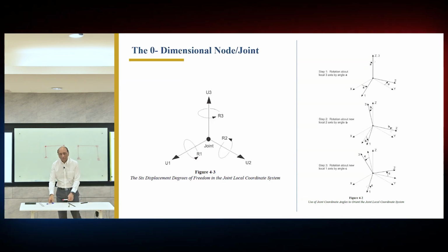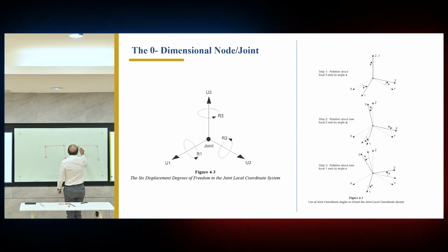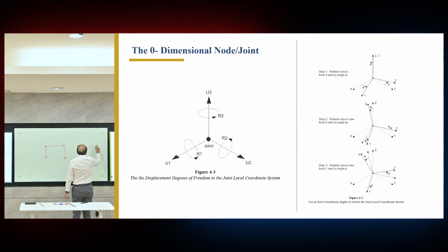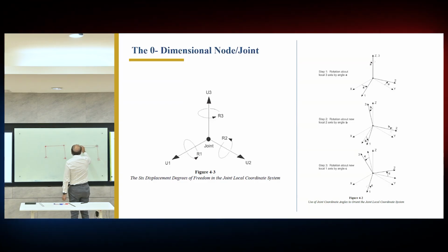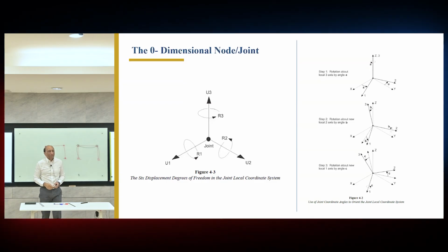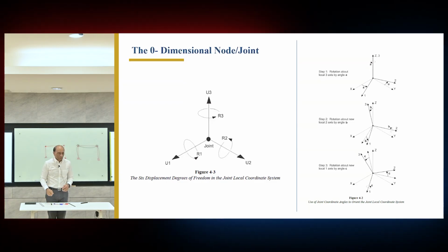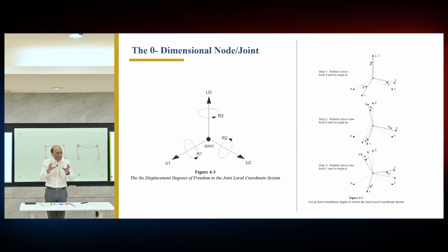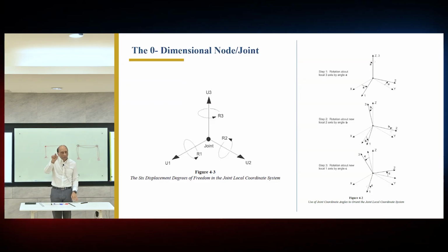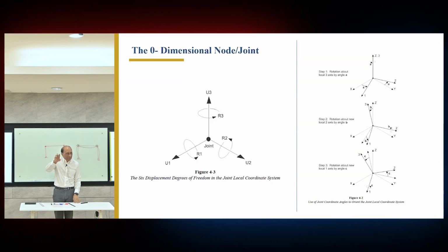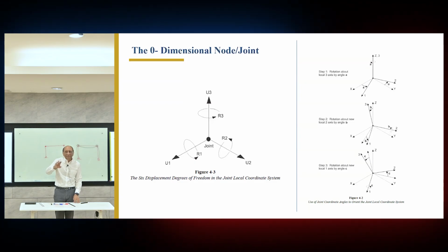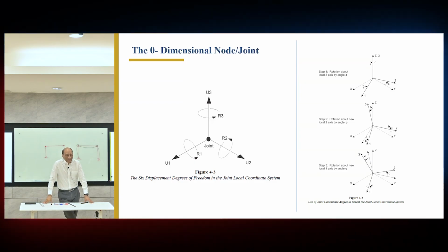And later we realized why he was doing that, because when you deflect this one like this, this will rotate. The node will rotate, and then it will tell you how this will reflect. Because at the joint, members have to remain perpendicular, 90 degrees. So it was a very good way to quickly visualize the deformation of a structure, because if you start with square node, the node should remain square after deformation, and all members entering the node must remain at 90 degrees. So that can automatically give you a very good idea how the members will deform.